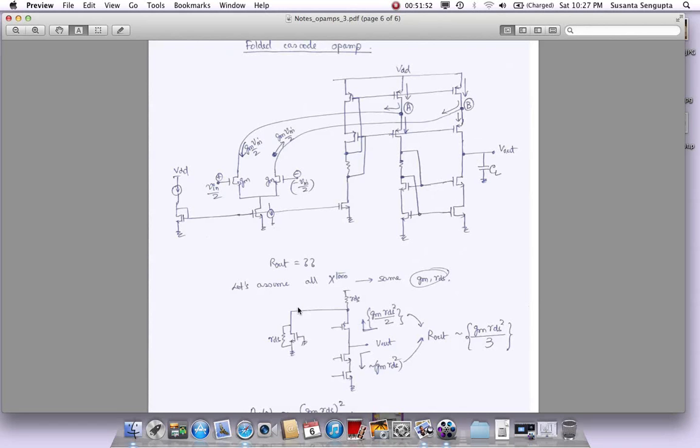The other thing that, before going into all this, I will also explain is when you do compensation, you can see there are no compensation capacitors here, because as you travel through various nodes, which you will see these are low impedance nodes, the resistance part of the impedance looking there would be roughly 1 over GM at these nodes, because we are pushing currents. Those tend to have far away poles.